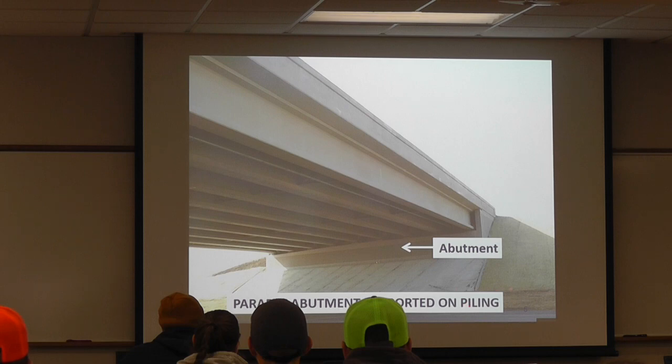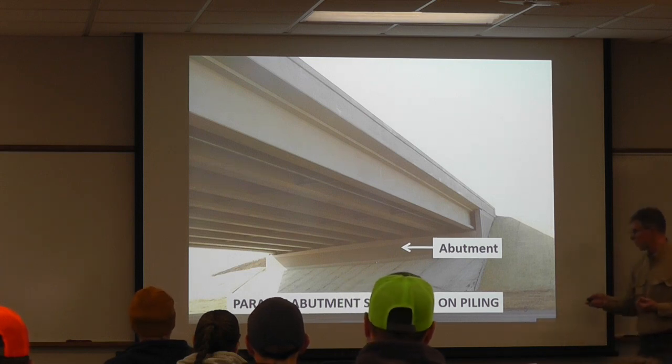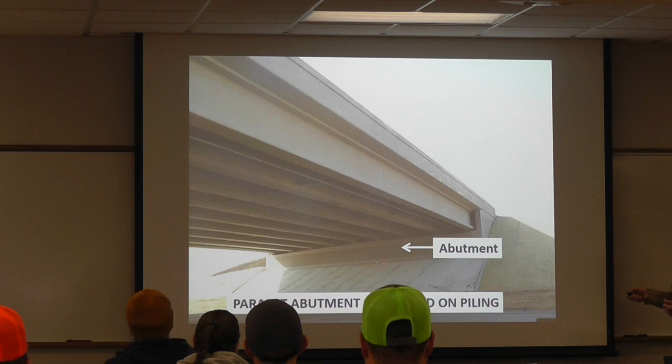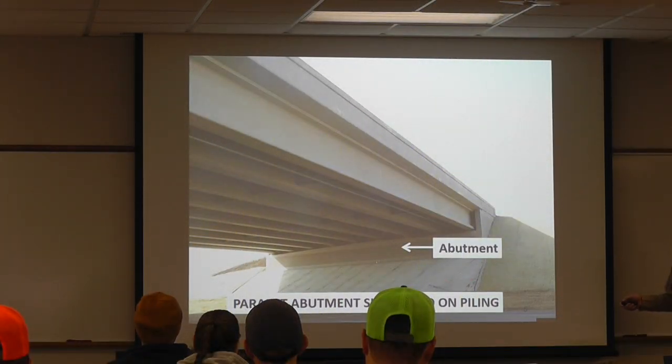Sometimes the footing will be way down at the roadway level, especially if they think in the future they may need to widen. But we have done some of these where the abutment was perched up in the fill like that. There's a slope paving coming down, and later the department says, well, we want to add another lane coming through this. Well, now all of a sudden you've got to retain that slope, and so we've gone in and put soil nail walls.